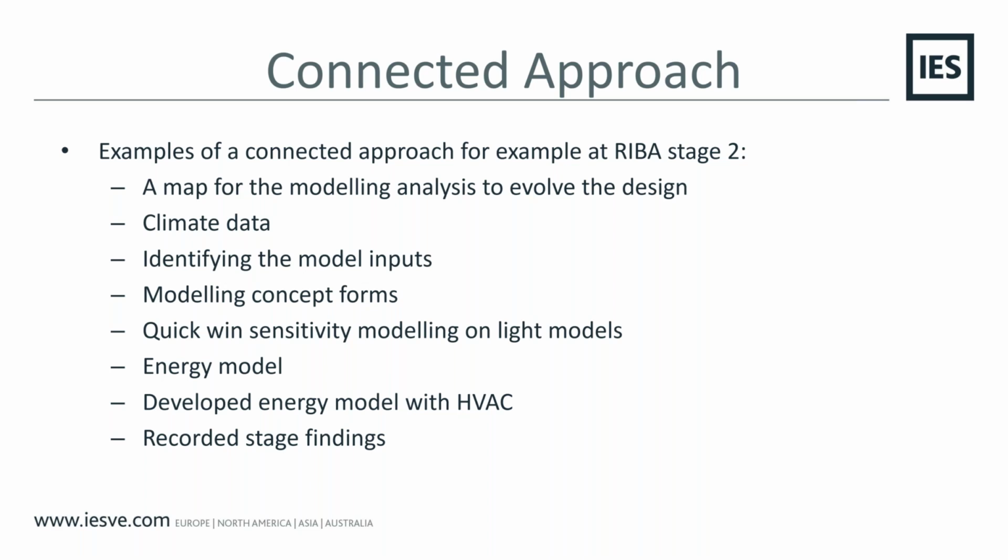What data do you have available in weather files at this particular point? Obviously, CIBSE have got a series of files available for locations, and that can include present day data as well as future weather files. But there are a number of other options available to source data. That's a library which is very much a growing resource for modelers. There's lots of files available to source, and it's a case of looking at what files are available and reviewing those in advance.